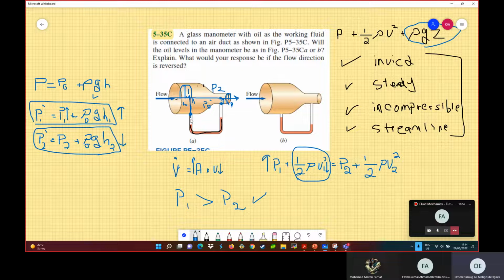And then go another distance, by another distance, go to this point. I want to see the pressure here. And also I want to see the pressure here. So I will add, for those terms, plus rho, but here there is an air. And I'm going down, so I will also add plus rho of the air multiplied by G multiplied by this distance H here. Let's name it H3 maybe here and name it H4. But at the end of the day, still you can neglect this term.